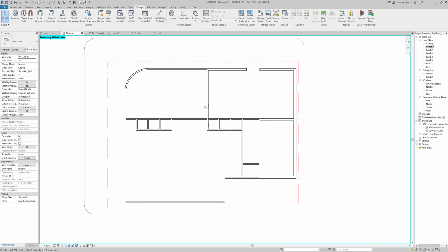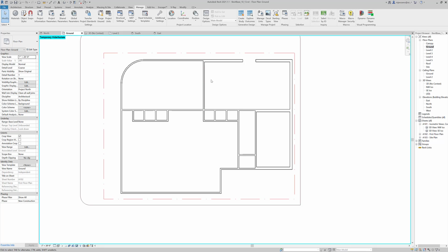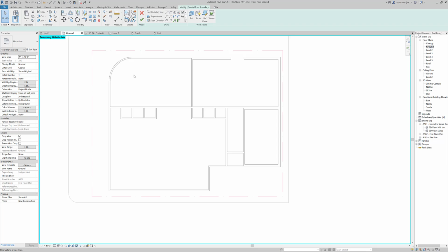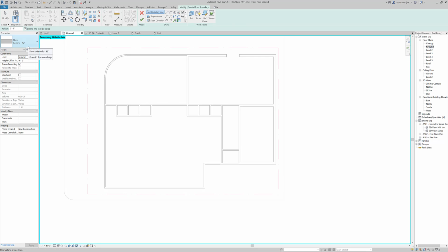And we might split it. In real life you would probably have some thermal breaks, and you would have some sort of waterproofing where there's a little lip or step to get in. But what I'm going to do is go to the architecture tab, and we're going to make a floor architectural. This is just a generic 12-inch floor, and there's a couple ways I could do it. I can start to draw it. I can also pick walls. So here's the pick wall tool if you're wondering, but I'm going to use the pick line command, and it sort of fills in if there are gaps.